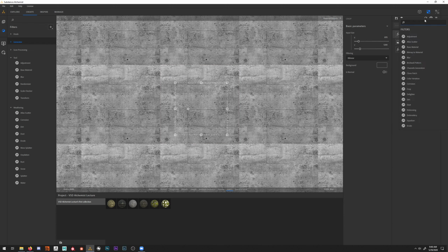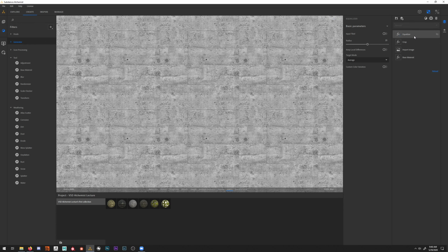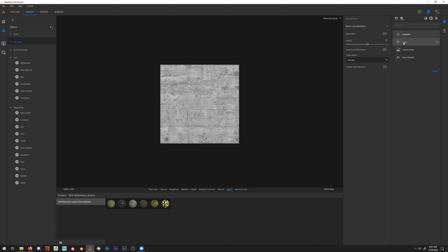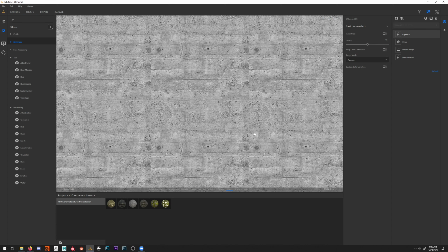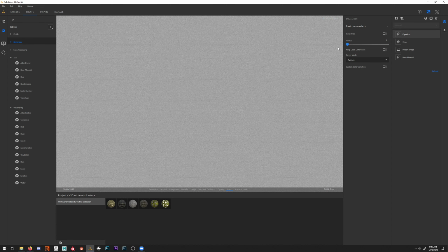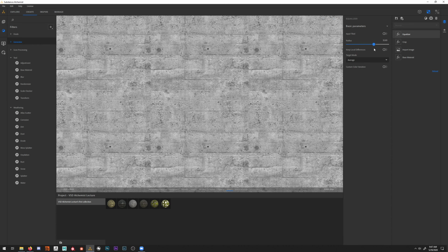So there is a node or a filter called Equalize, the equalizer, that will balance all the lighting. In fact, it fixed that problem for us. It just went ahead and fixed it, right? It balances your highlights, it balances your shadows, and makes it a lot more tileable, right? So again, without it, we get that problem there. So turning it on and off, this is going to tile very nicely, actually. We do have other controls, so if you need to adjust the radius, that doesn't look too hot. So you have to find that sweet spot to get it to look nice.